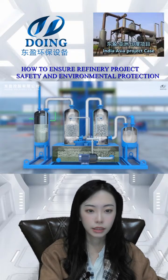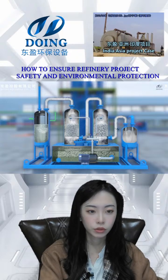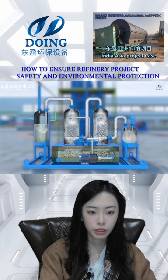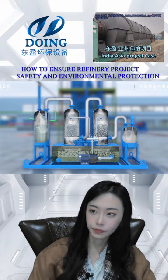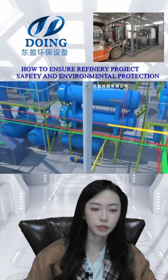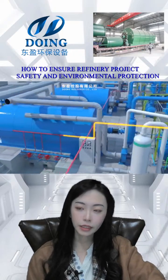Inside is a physical filter to disperse the gas into the tail gas and make it fully contact with the moisture to deodorize it. This is a water seal. You can see here, the purified tail gas will be recycled to the reactor through the pipeline to heat it.